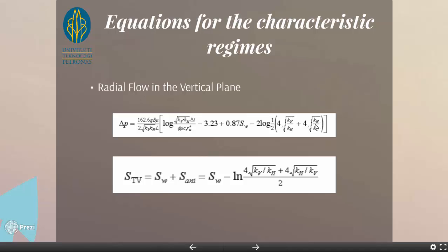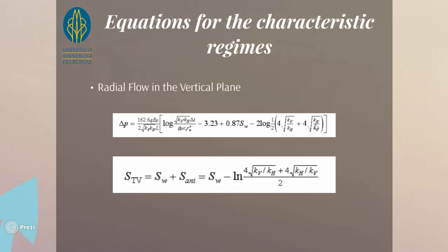The second logarithm corresponds to the negative anisotropy skin resulting from the equivalent wellbore radius, which is rwe. The total skin factor, which is Str, measured from the early time radial flow analysis, combines the wellbore mechanical skin factor Sw and Sne, which is the negative skin anisotropy.